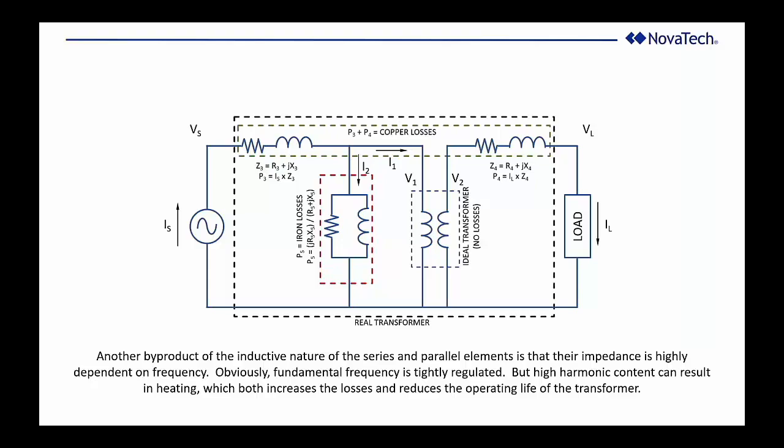There is also a temperature component to losses, but by and large, most transformers are either low enough power that they can operate at ambient temperature regardless of the rise and fall of the seasons, or they have fins on distribution transformers or fans on liquid-cooled transmission transformers. So to the extent that temperature-related losses are a factor, the temperature is typically controlled to minimize the impact of the temperature on the losses.